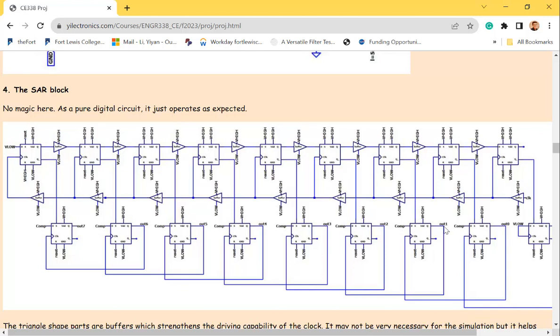These are the D flip-flops holding the data here, the final result, right? And now if there's no rising edge happening to any of the D flip-flops anymore, what's happening to it? Yeah, it's memory. It's going to memorize all the final state. It's not going to change anything until the next reset. So it's actually okay. You can wait 100 cycles and it's still the final result. They're not changing. But we don't want to wait that long because we want to make the ADC faster.